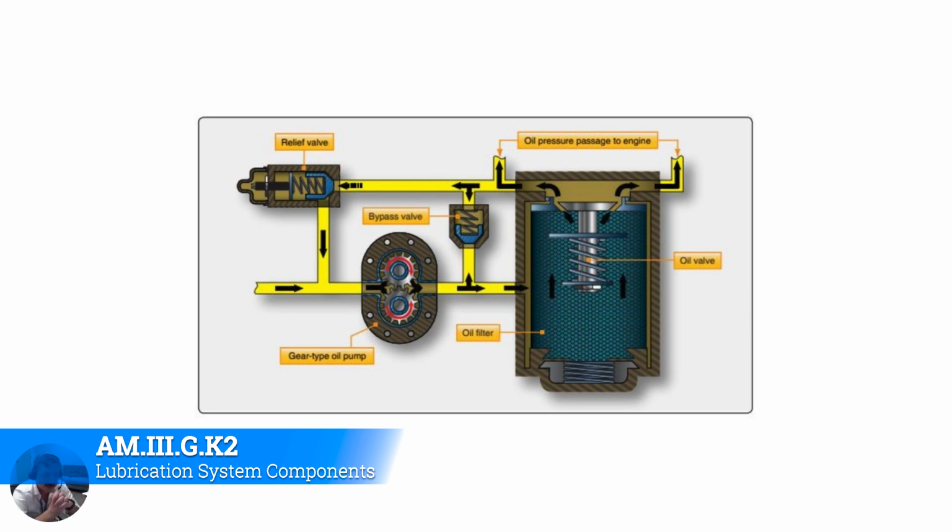Typically, it's an indicator that there's not enough oil in the system. Now, you could have a situation where the settings are off, or maybe something else has happened. But the only way that you get really low oil pressure is if you have air in between those passages of that sprocket, and that air then allows the oil to expand and not be so pressurized. So therefore, you likely have a low amount of oil in the system.